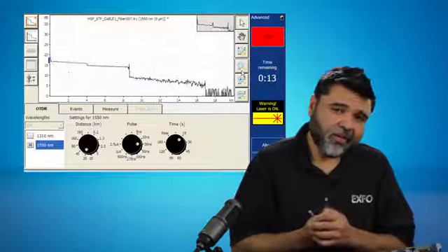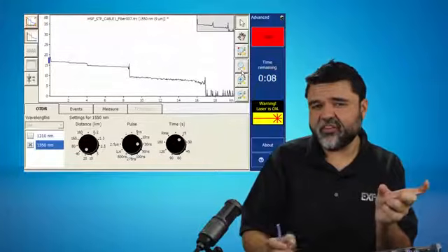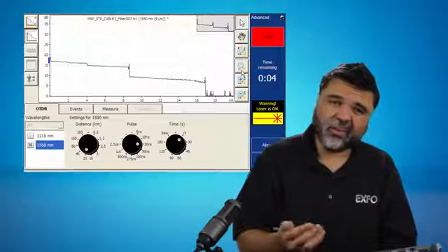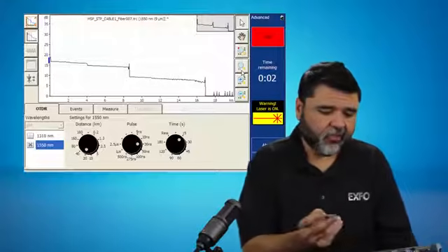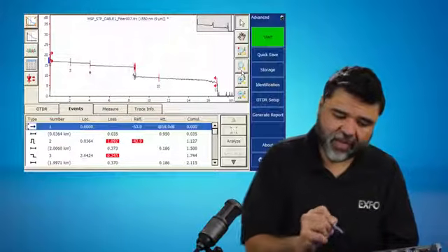And this is basically how I test with an OTDR. I'll shoot it in auto mode. I'll determine that the distance is right and the time, because those two are no-brainers. Then I'll keep dropping the pulse width down until I get a noisy trace. So look at this trace here. After 15 seconds, I have quite a bit more noise towards the end there.